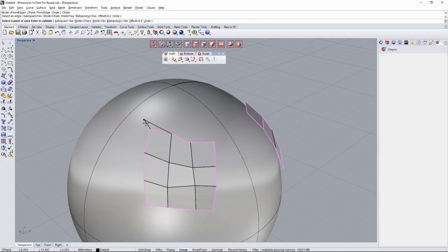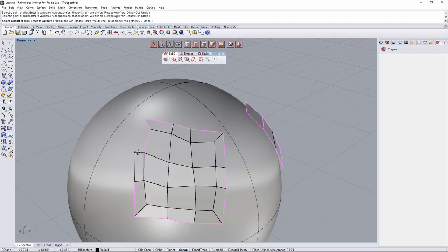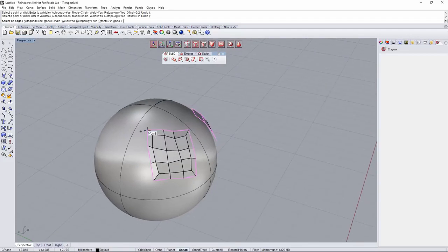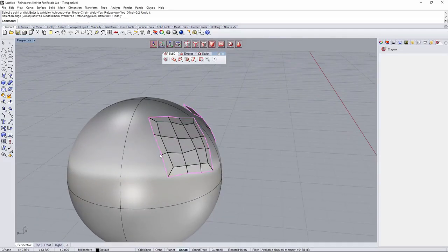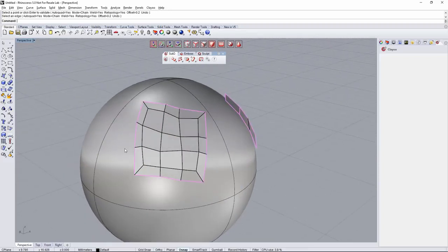But then when I click on the first point and I click on the second one, it's going to automatically detect the angle, the order in which I'm picking the points, and it will make me click just one time to create the face, to generate this loop of faces so fast. So that's so interesting when we are just retopologing one model to go faster.